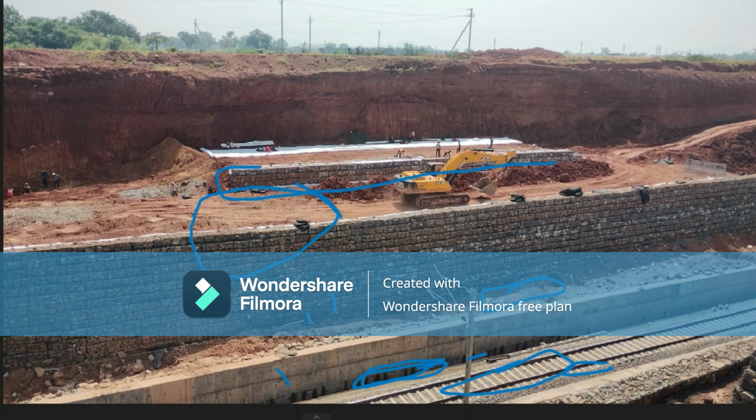There, at first they provided the foundation, usually of concrete, and then started the gabion block stack on one another, with the geogrid along the slope horizontally. So this is the second step, and this will be the first step. First we will see how the first berm to the second berm is constructed.